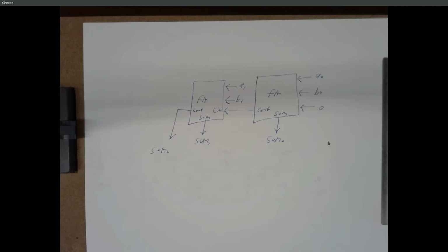Every circuit we've built so far in here, we start with a system diagram, we go to a truth table, we write equations directly from the truth table using a sum of products or a product of sums, possibly using K-maps to simplify. Here we're not doing that. We're looking functionally at what we want our circuit to do, which is pencil and paper addition. Add one column, bring a carry over, add the next column with that carry, and so on. And then we're building a circuit to basically do that. And the result is we end up with a simpler circuit.